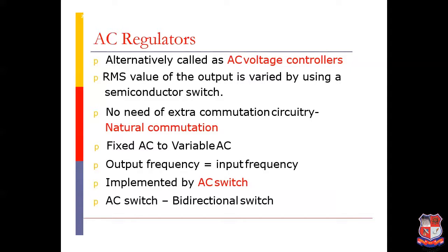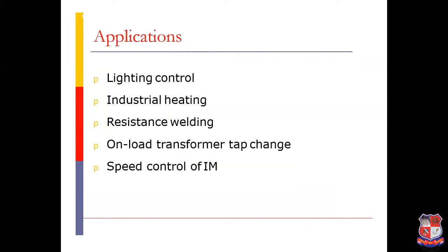Therefore, AC voltage regulators are suitable for some specific applications like lighting control, industrial heating, resistance welding, on-load static transformer tap changers, as well as speed control of induction motor.